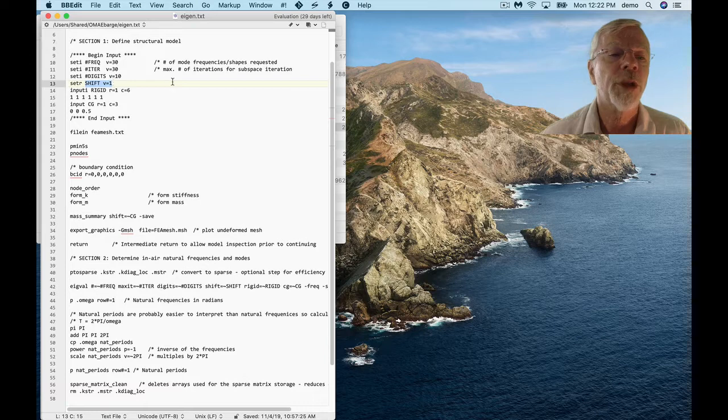So we're going to be calculating the eigenvectors and eigenvalues for a free structure, a structure in air with no restraints, so that we know the first 6 are going to be 0, which means the stiffness matrix is singular. So we need to apply a so-called mass shift to be able to calculate those. I've found personally that I've never found a value of 1 not to work for me. But you can change it if there seems to be some problems.